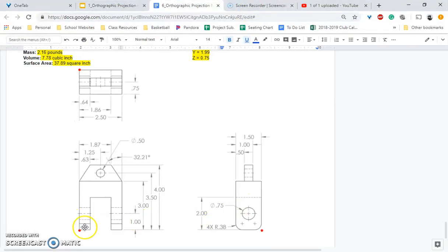So all of this extra stuff in here, if you follow that over, you see a hidden line, a center line, and a hidden line. So if we follow that over, that's this circle. And this line here is where it starts from the straight into the curve. So we're not even going to use any of this on our front view. All those lines are going to be created when we make this stuff on our right side view. So we're not going to use that 1 yet.